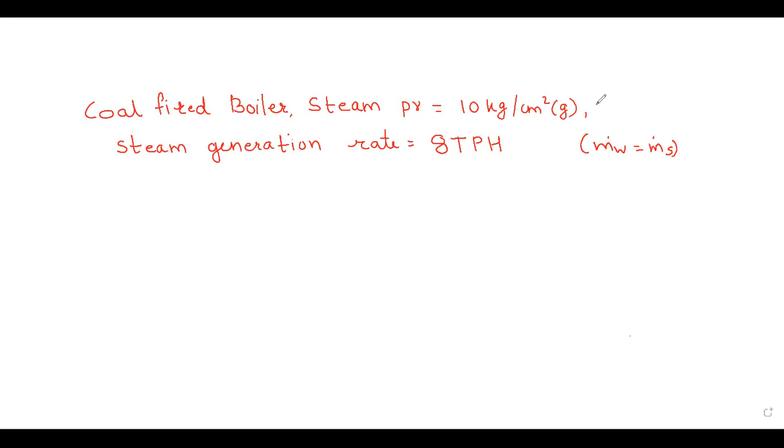One more piece of information is noted down, that is the temperature of the steam. We get it from the thermocouple, and these thermocouples are connected, and we can read those readings using the temperature indicator which is available on the boiler. So the steam temperature reading is, let us say, 180 degrees centigrade. This information is also with us now.